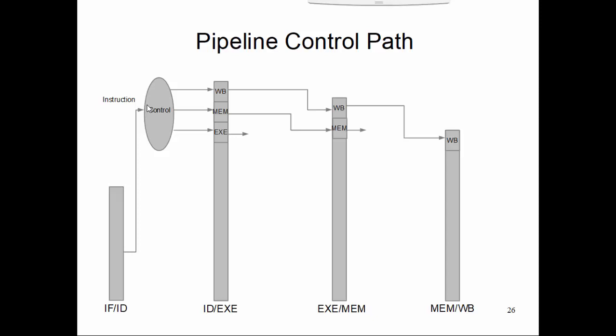The values of control signals depend very much on what instruction the controller is executing at this moment, right? So after the instruction fetch, your instruction is decoded and the controller decides on the further control signals to be given to those different resources like the ALU, register file, memories, etc.